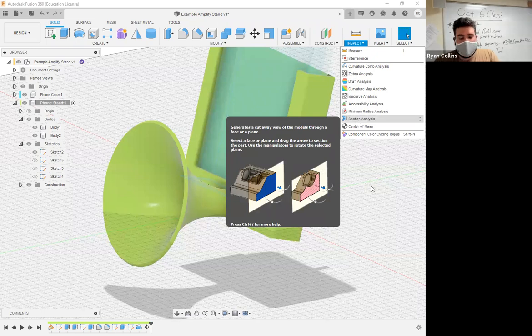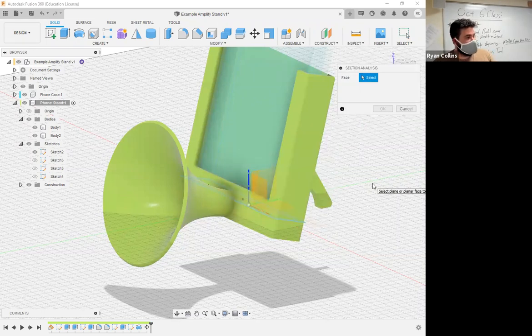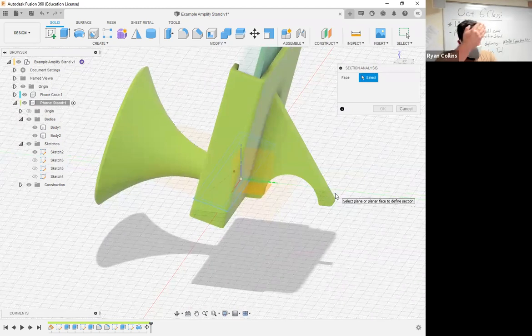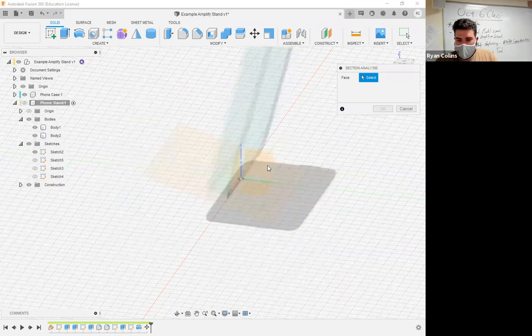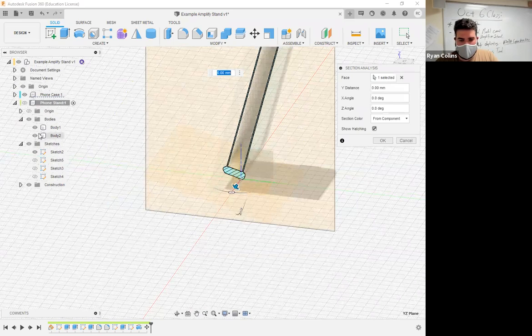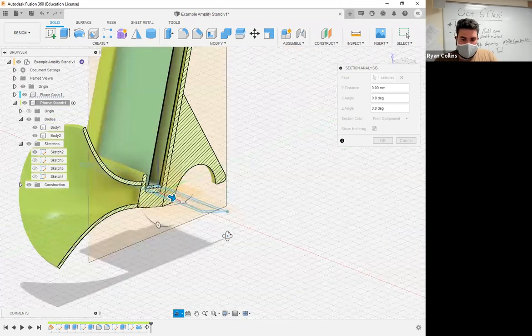All right. Now it is based off of construction planes, or rather your origin planes. So if I want to cross section off of the YZ plane, so the half and half there, select there if I can get to it. Problem is, a lot of times your models and such get in the way. So fine. Hide the whole thing. Now I can actually see what I'm doing there. Great. Unhide the whole thing. And that is just smack right in the middle.